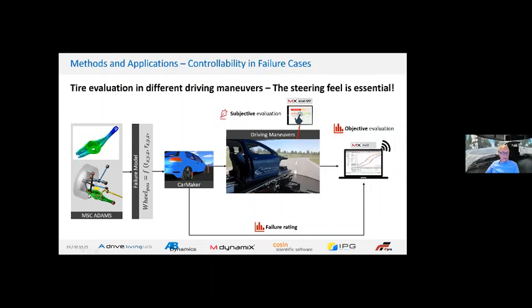And what we have done is we have transferred the failure behavior by a simplified wheel behavior model to CarMaker, and so we can then imprint this error to the certain wheel in time behavior, under static and transient conditions, and can bring the error in defined use cases or defined driving conditions, and have a look how the driver can control that, and what are the limits where it is not possible for the driver to control that.